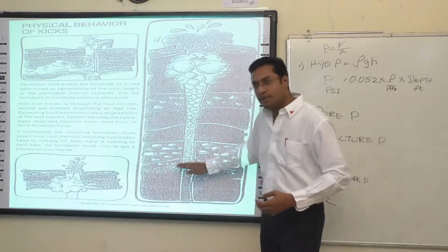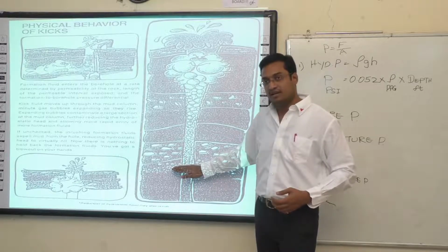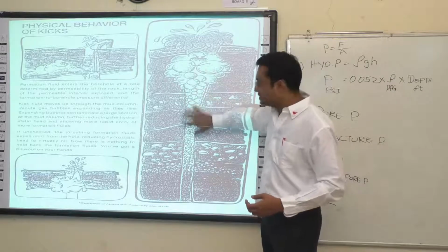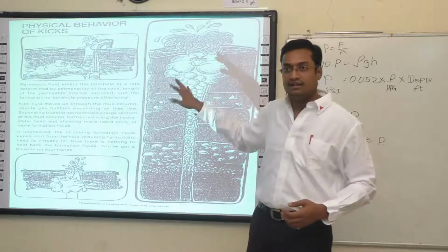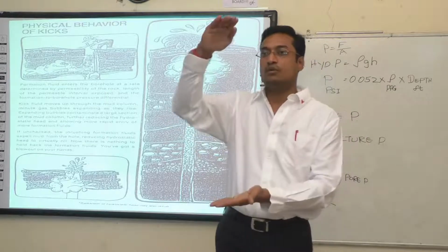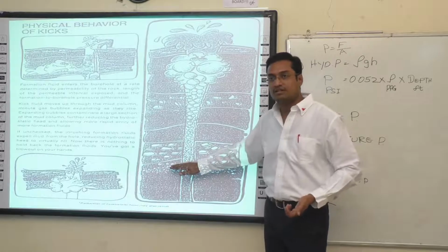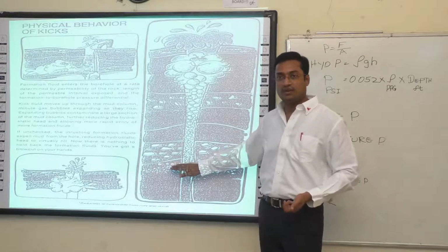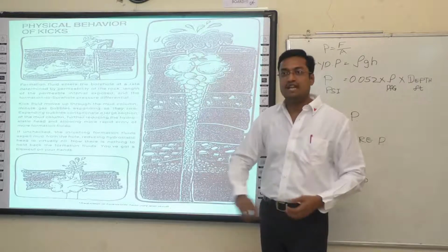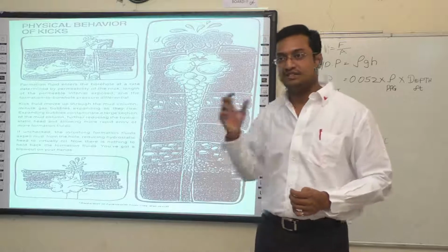Keeping the bottom pressure constant, same as the formation pressure, you circulate out the kick, the unwanted influx, out of the well, and make sure the correct density of fluid is inside the well to bring it back to balanced condition. That is successful well control. So when you open the BOPs, there should not be any pressure, there should not be any fluid. That is well control.